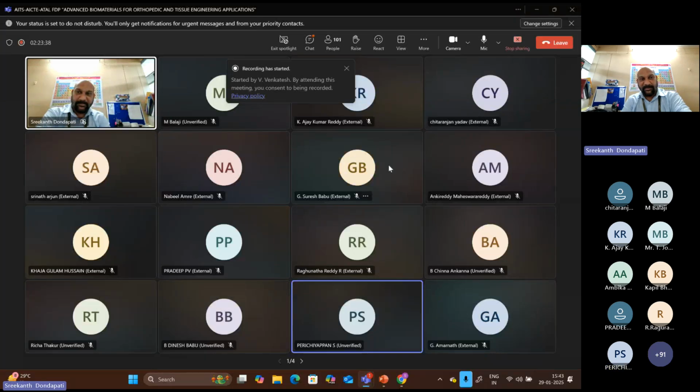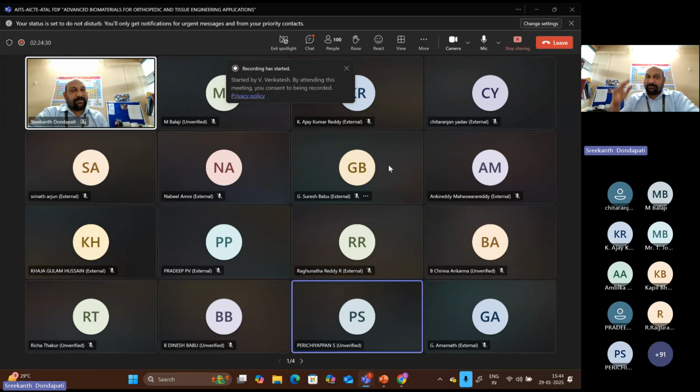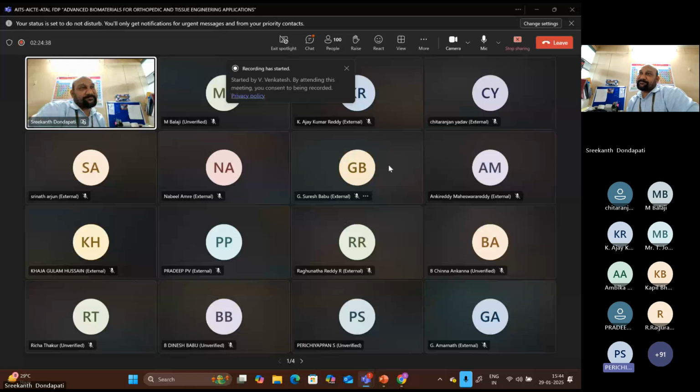Sir, excuse me, one question. Magnesium is an absorbing material, sir, it can be absorbed, no? Yes, it is a biodegradable, degradable material. And we are giving the coating. I have presented here about plasma electrolytic oxidation coating to reduce the corrosion rates, not to completely arrest the corrosion, because we ultimately need the biodegradable implant, not a permanent implant. So I want the degradability, but I just wanted to reduce the corrosion rates. Because if it is too high a corrosion rate, the hydrogen evolution is a big problem, and it can also be toxic to the body. So that's why we need to reduce the corrosion rates, but we should not arrest it completely, because ultimately we are talking about biodegradable implants. Okay, thank you, sir.